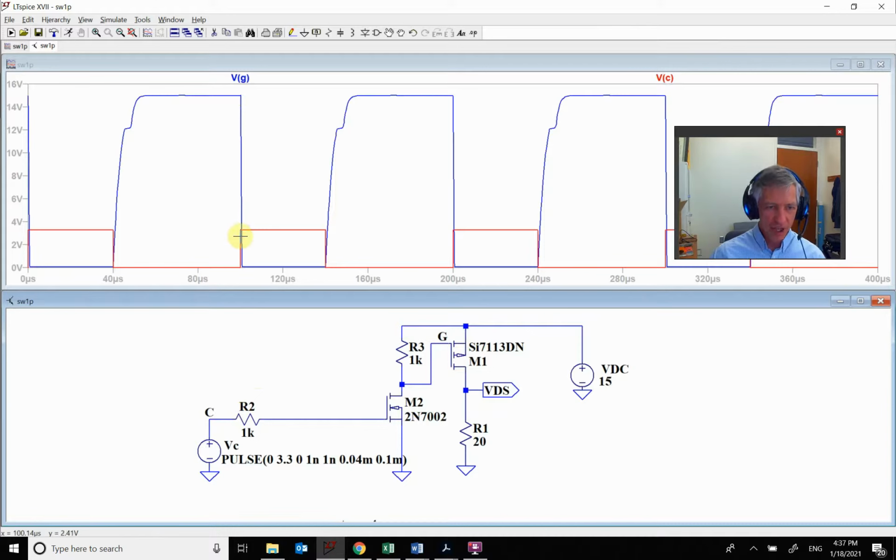When this voltage goes up, it takes this transistor and moves it up into triode. When this gets moved up into triode, this point becomes a short circuit. So the Thevenin resistance seen by the capacitor, from this gate to source, when we're trying to drain these capacitors, is basically being shorted, and so my gate is tied to ground, and that's a low resistance, and so it's going to operate really fast.